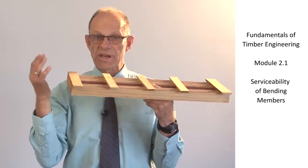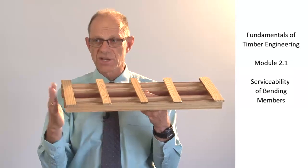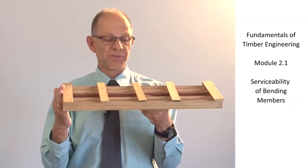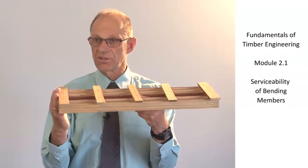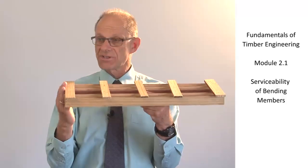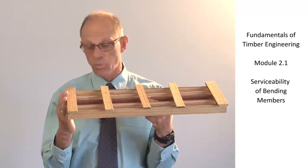Now, this is where the duration of load is important. If we're thinking about crowd loads, crowds don't stay on the floor for a long period of time, certainly not more than a year. They're on for less than a day. So that's classified as a short-term load, and the J2 factor is 1 for that.